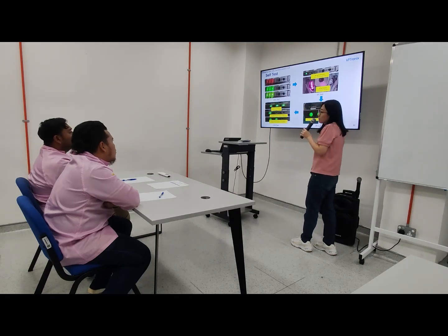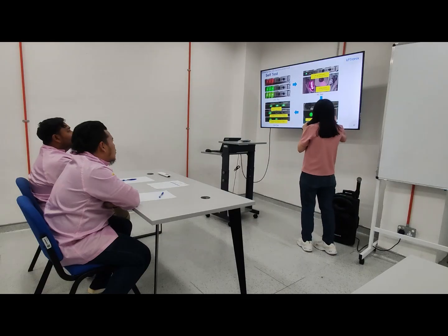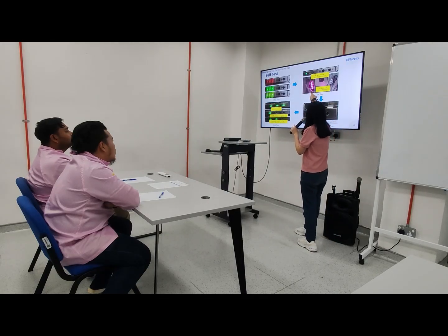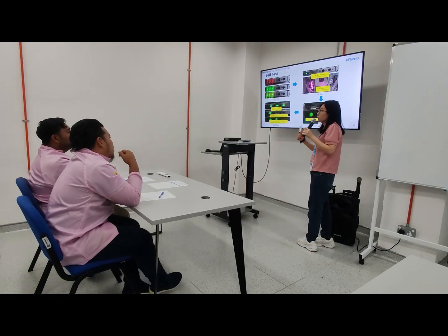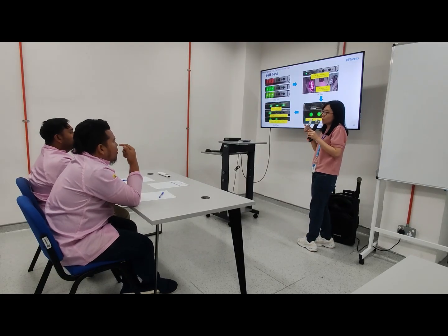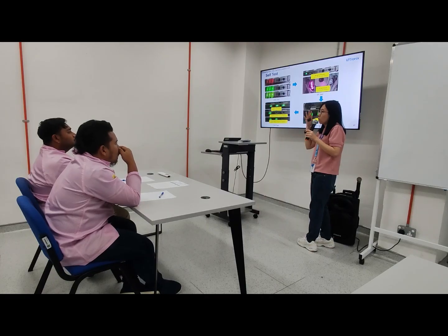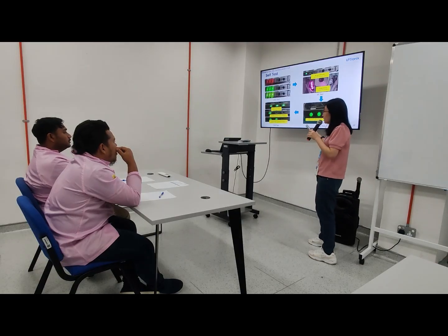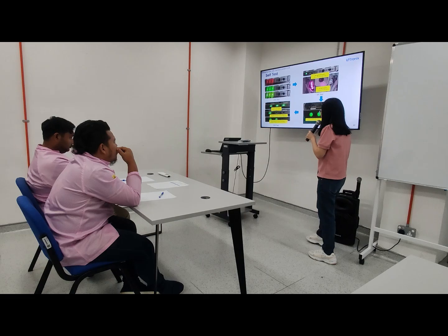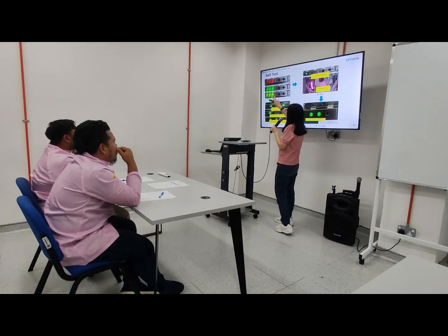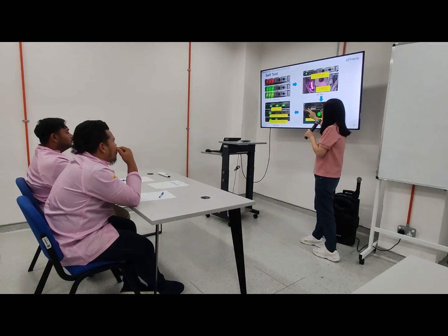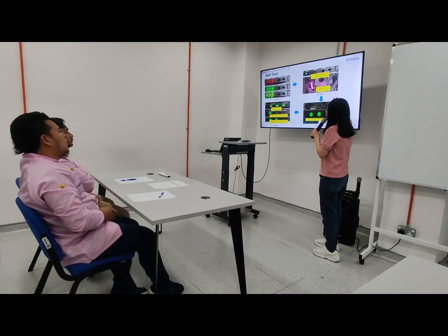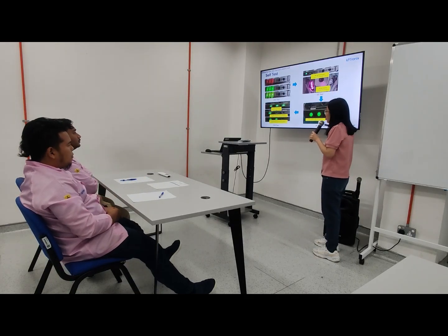Next step is the IR test now. IR test means we need to check the LED quantity and also that the brightness is average. All the 4 LEDs must have the same color brightness. After the IR test, then we'll go for the next test. Actually, all we press is this one, the sync button. And after this, we'll press the sync button to go to the next test.